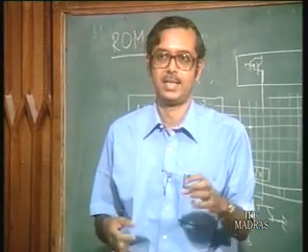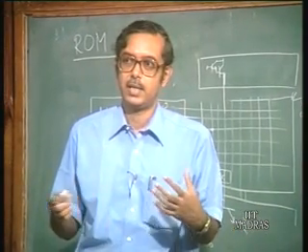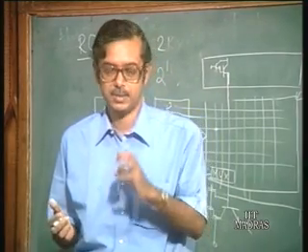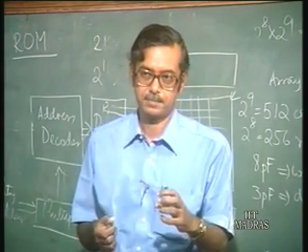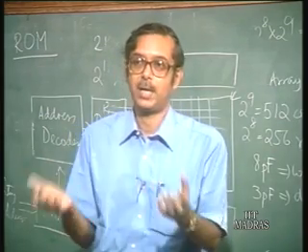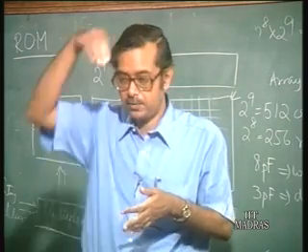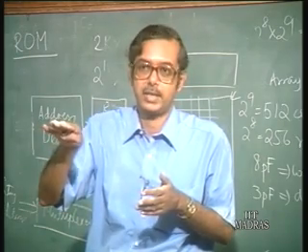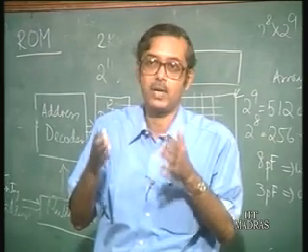We have seen that BiCMOS retains the advantages of CMOS. At the same time, by introduction of bipolar transistors, which have certain specific advantages compared with MOS transistors, there is the larger drive capability of bipolar transistors. That is, they can drive much larger currents. Because bipolar transistors are vertical, the current flows in a vertical way, compared to MOS, where the current flows in a horizontal direction along the surface. So, bipolar transistors can provide a lot of current.